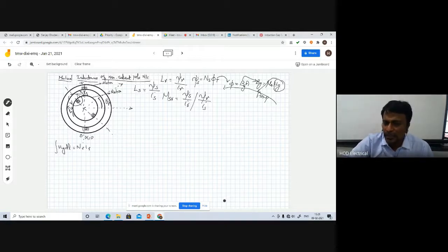Taking the closed path, Hg times the air gap length plus the return path Hg times the air gap length is equal to nr ir. From that, Hg is equal to nr ir divided by 2Lg.